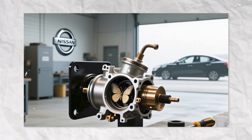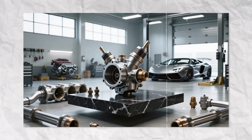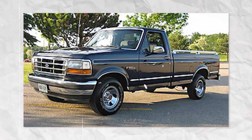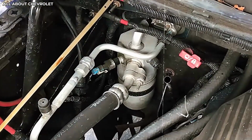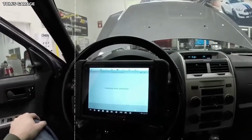Park on level ground and gather your tools. You'll need a 10mm wrench or socket to disconnect the battery terminal. Pop the hood and locate your battery. On most F-150s, it's under the hood on the passenger side. On some models, it might be under the rear seat or in the spare tire well, so check your owner's manual if you can't find it immediately.